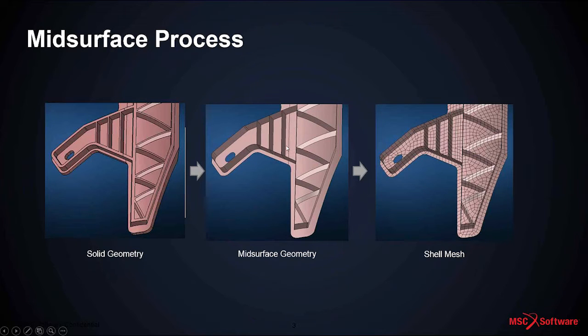It might be characterized by hundreds, maybe thousands of individual mouse clicks, or thousands of individual steps just to finally get to your geometry. After that, you might then take additional time to go ahead and create your mesh that might be used in FEA. You might want to also assign some thickness properties to the sections too.